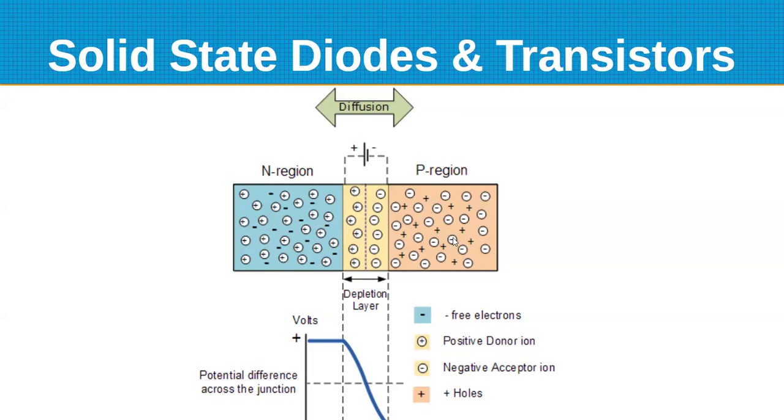If this was germanium material, which you do the same kind of stuff with, but germanium isn't used very much except for some diodes, the voltage would be 0.3 volts. Now, the reason that's important is for you to get current to flow from the P region to the N region, you have to overcome this bias voltage. So if you apply a voltage between this end and this end, and it gets up to greater than 0.7 volts, current will actually flow from the P to N region. And that makes a diode.